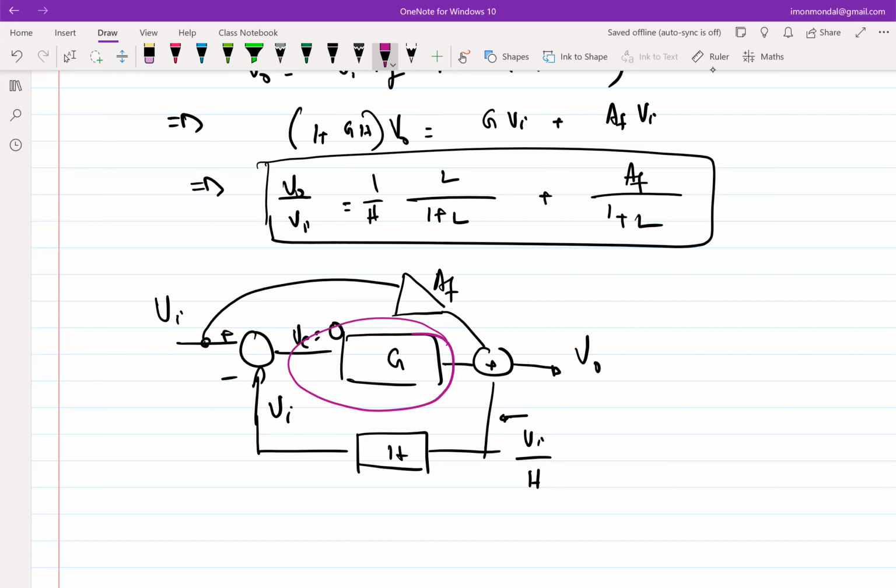It doesn't matter whether you have something connected through here. It doesn't matter if you have another input from somewhere, not here inside the loop, sorry. If you have another input from somewhere, because everything is immaterial kind of, isn't it? Because ultimately the loop, it seems like the output is being set by the feedback path. Output is not being set by the forward path, right? This is another crucial part of a negative feedback network, that in a properly designed negative feedback network, you can always figure out the output by what is connected in the feedback path, right? Even though the output is being driven by the forward path, the value of the output doesn't depend on the forward path.